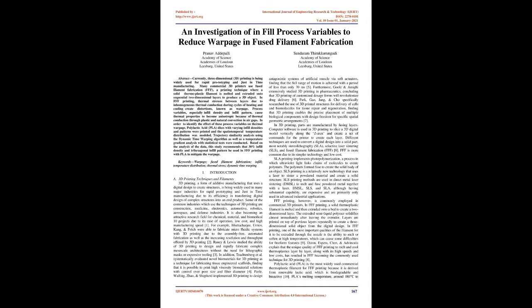Many commercial 3D printers use fused filament fabrication (FFF), a printing technique where a solid thermoplastic filament is melted and extruded onto sequential two-dimensional layers to produce a 3D object. In FFF printing, thermal stresses between layers due to inhomogeneous thermal conduction during cycles of heating and cooling create distortions,